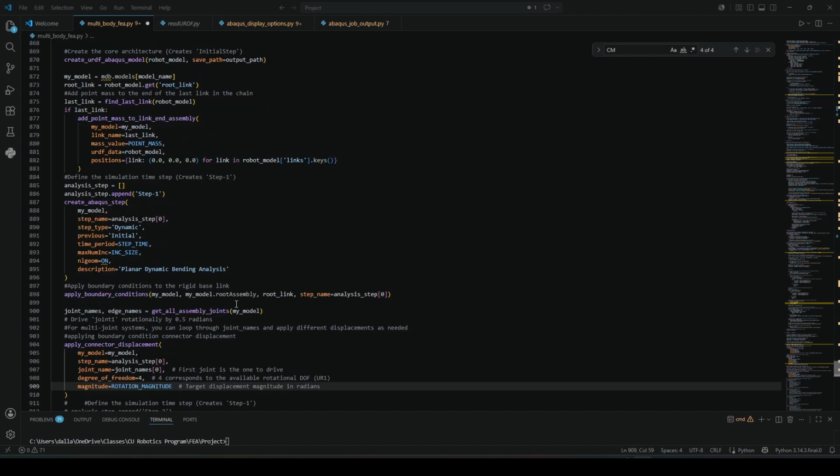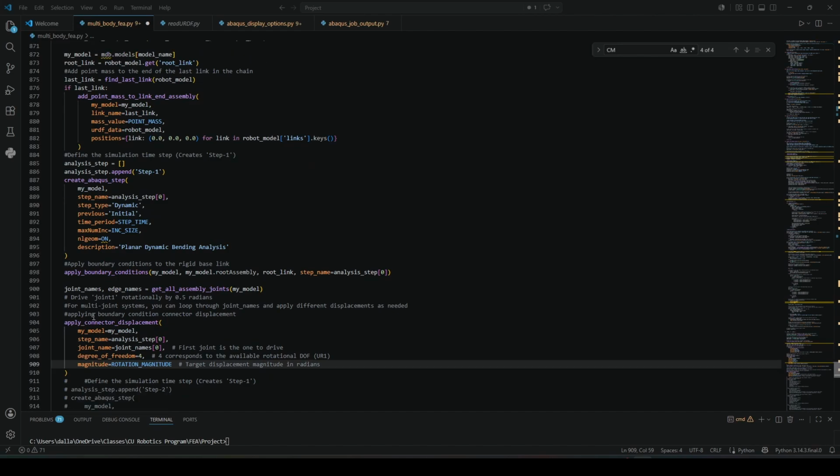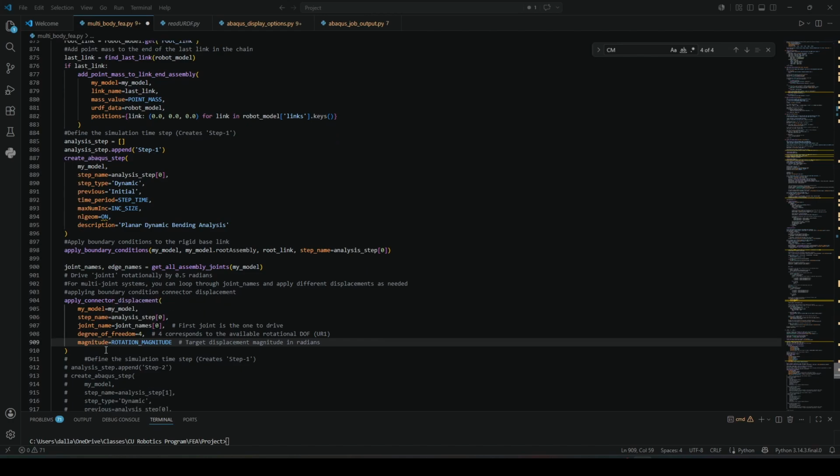elements. You can't apply displacements to a node like you normally would in the model. If you do that, it doesn't recognize the reaction forces on the connectors. It just allows the connectors to be kind of free swinging. So you have to apply a specific connector displacement. So I've called out specifically the connector displacement and provided the rotation, which would be 45 degrees.